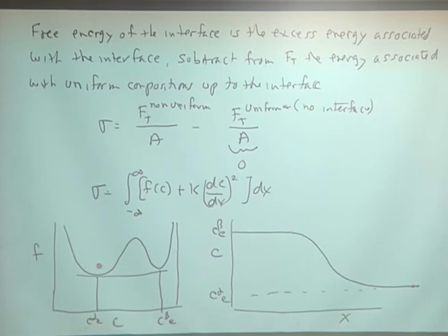So the free energy of the interfacial energy has to be related to the free energy function in this region here. Okay? So that's the first thing. The other thing that's kind of interesting that you can think about is if you look at this composition here, you go over to here, you go up, you're within the spinodal.